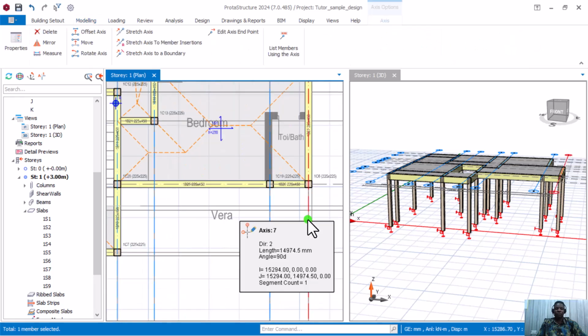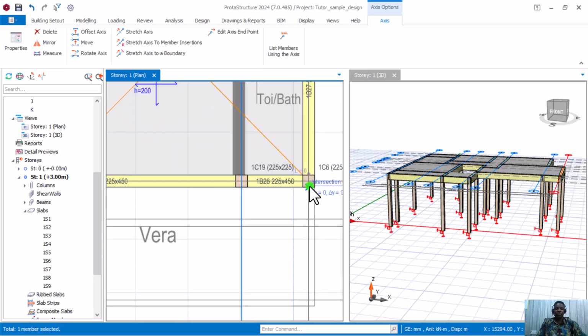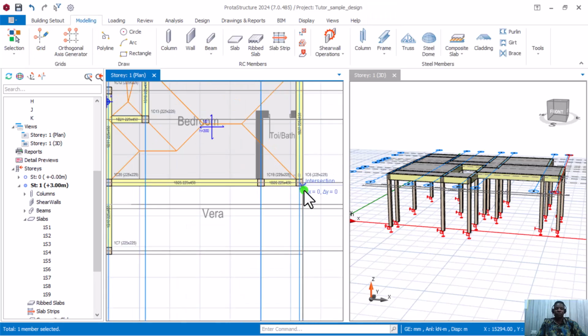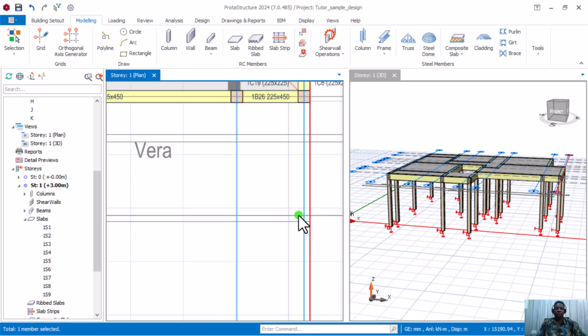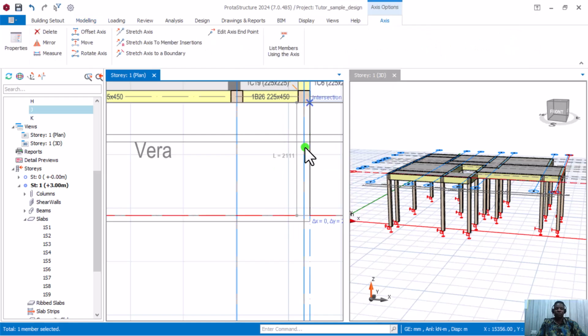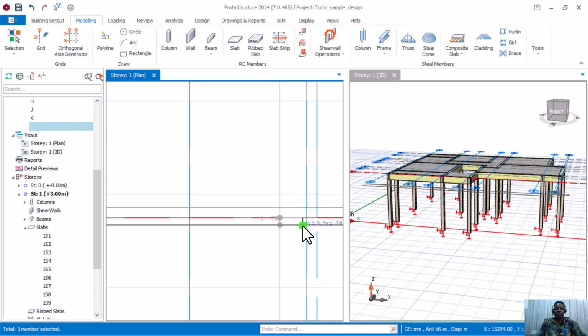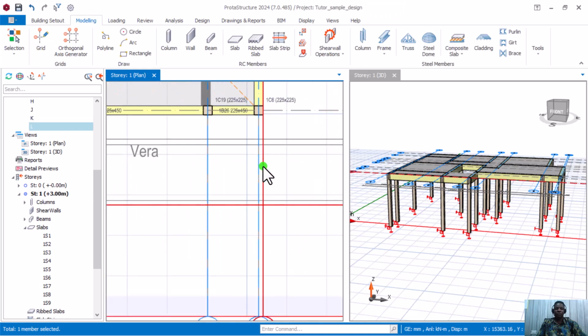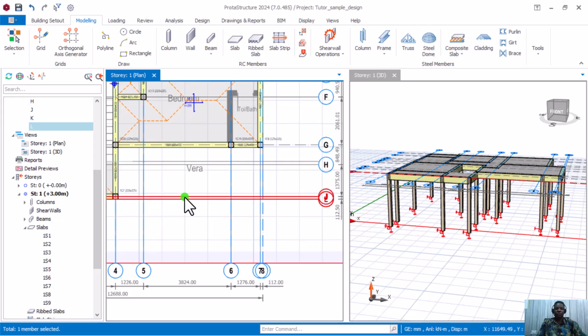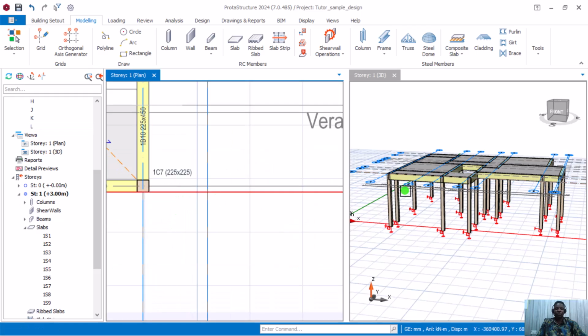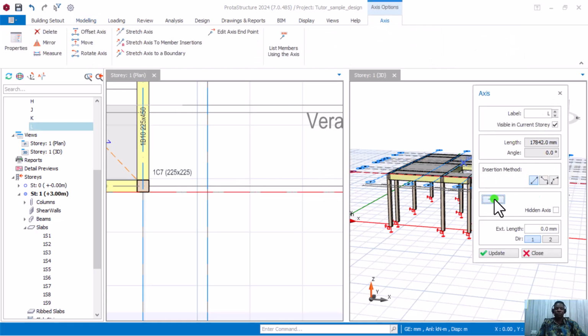Okay. So you just click this grid and go offset. Go straight down to this point. Now we're going to click on this grid, and we'll also right click and click on offset, so that I can get the edge. If I use this grid L, I'm not going to get the edge of this. It's going to give me inside. So we'll just double click so we can make that grid a ghost, and we'll hide it and we'll say update.